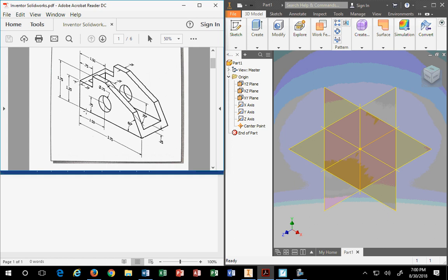Now the bigger question is, do we start with the front? Or should we start somewhere else? The short answer is you start in the plane that has the most geometry in it, meaning the most unique silhouette. Did you hear that? So the footprint, whatever plane has the most geometry that you can pick off at the same time, that becomes your front plane.